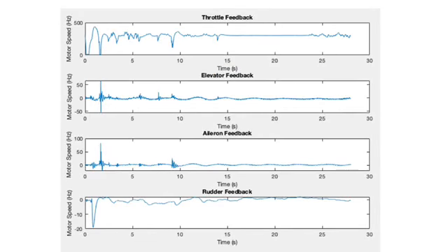In our original system, the feedback controller for throttle required linearization of the UAV's state equations for vertical height and vertical velocity around an equilibrium point. We successfully replaced this control law using dynamic inversion to eliminate the UAV's nonlinear dynamics and replace them with a model that follows a second-order transfer function. Since this control law is not dependent upon linearization at a certain point, it is perhaps more robust to different flight commands. Overall, we achieved a stable hover using dynamic inversion to track a height command.